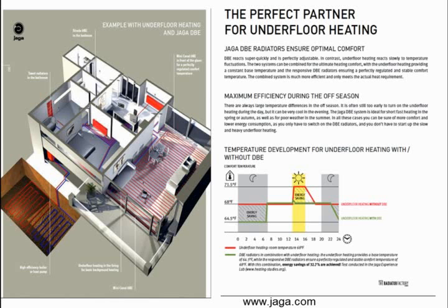And the same thing was true when we talked about solar. The lower temperatures that you can run up to the solar collector, the higher the performance, the higher the efficiency. So with that in mind, we want to look for some systems that can operate at low water temperatures. And when I talk about low water temperatures today, I'm thinking maybe below 120 degrees F. What's interesting now is there's some products coming out on the market that can work at those temperatures and give you pretty good outputs. Probably the most familiar one to most of us here would be a radiant floor slab.